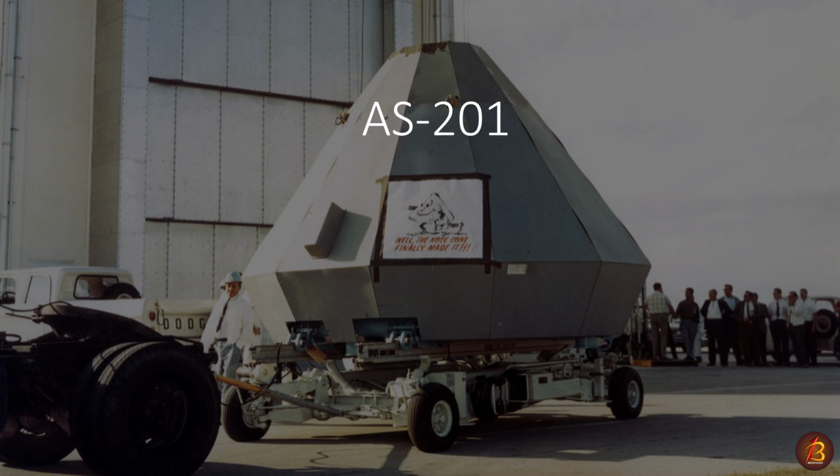So, in the building of it, this was the first flight of the Saturn IB rocket, the most powerful rocket up to that time, with a first stage thrust of 1.6 million pounds, built on the 10 successful launches of its predecessors, because remember, we had Mercury before Apollo. The Saturn I rocket flew between 1961 and 1965. The Saturn IB used 8 upgraded H-1 engines on its S-IB first stage, but the most significant improvement over its predecessor involved the use of a new upper stage called the S-IVB, powered by a single J-2 engine using liquid hydrogen as its fuel. The larger Saturn V rocket used a version of the S-IVB stage to complete